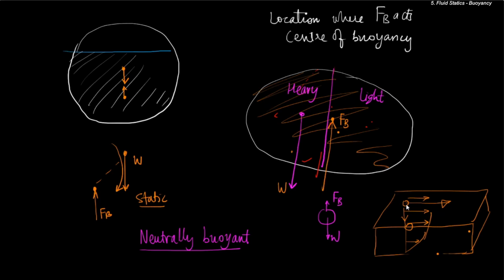So for having tracer particles to measure flow fields like I just mentioned, we must have particles which are not just neutrally buoyant but also quite small, so that they do not experience appreciable drag. So if a particle experiences drag, its velocity will reduce in comparison to the flow, and thus it will not give us the true indication of the flow field. But more on this when we study viscous flows.